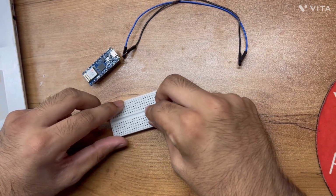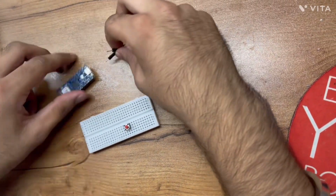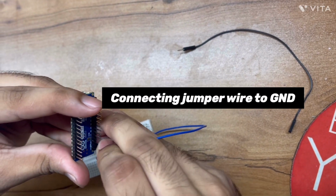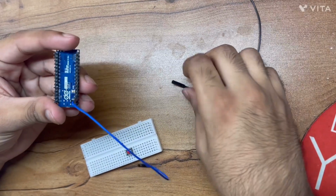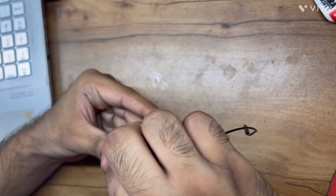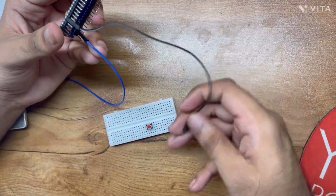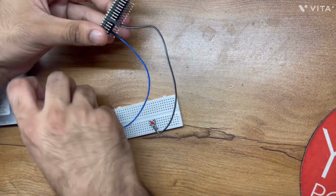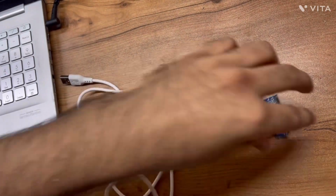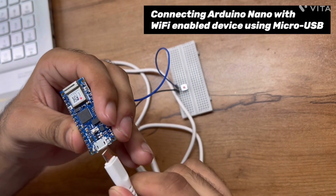We have first installed the push button to the breadboard, as you can see in the video, and now we have connected one of the jumper wires to the ground pin of the Arduino, and the other jumper wire is connected to D2 of the Arduino Nano respectively. Now further, these jumper wires are connected to the push button on our breadboard. Now at last we are establishing the connection of the Arduino device with our laptop using the micro USB cable.